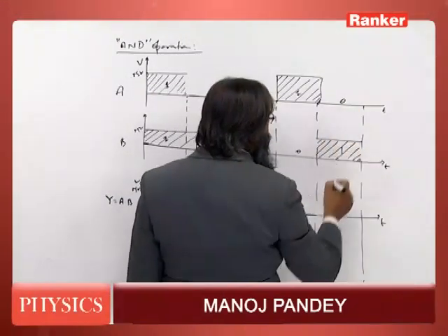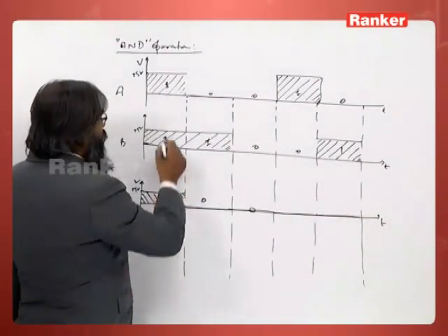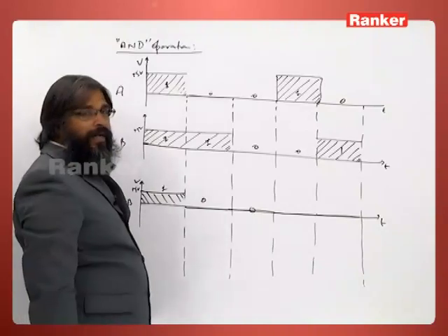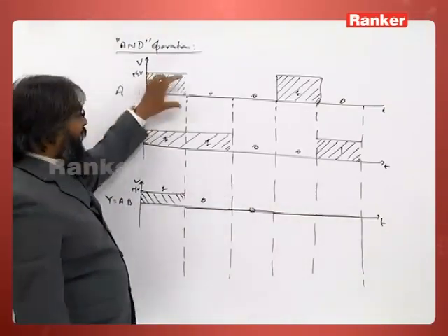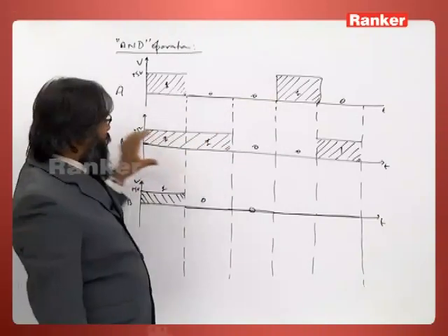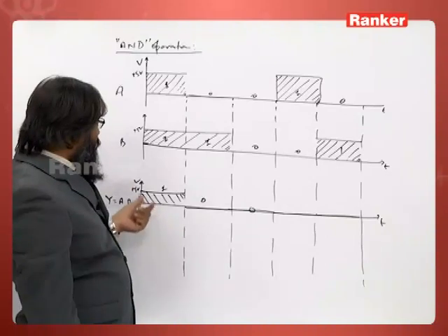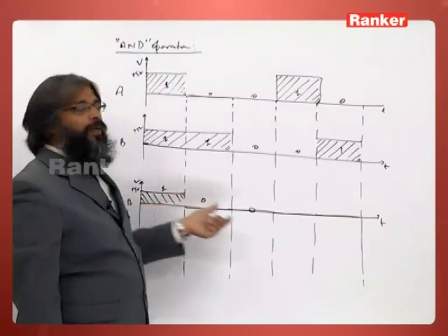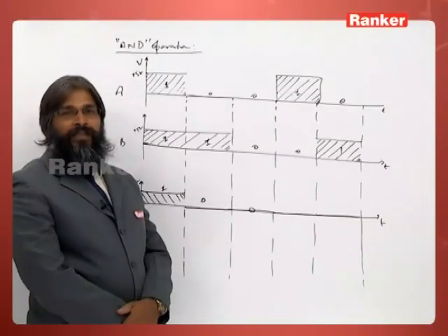Here this is 0 and 1. So, we will get 0. So, I will get high only when both the inputs are high. So, in this way, you give A waveform like this, you give B waveform like this, you will get the digital waveform at y as this one only. This is what A and B is.